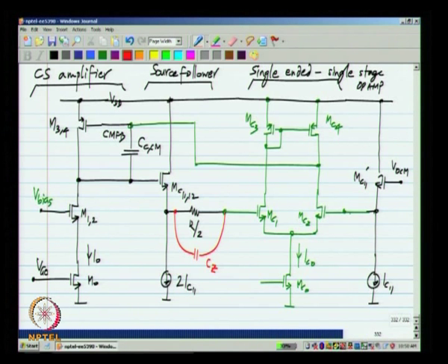So, this is what we need in order to have a stable common mode feedback loop. Now, you see that the circuit looks exactly like the 2 stage amplifier, where the CCCM is the integrating or the Miller compensation capacitor. Okay. And just like with the 2 stage op amp, you can also add a 0 cancelling resistor in series with this.